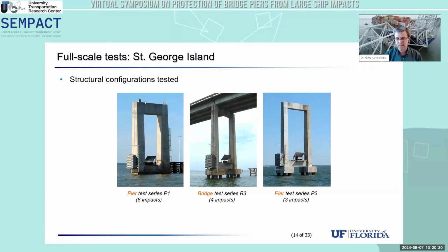The superstructure had been removed. We tested pier 3 in what we call a bridge configuration, where the superstructure was still in place. And then we tested pier 3 again after the superstructure had been removed, because we were very interested in the effect of that superstructure, not only on the generated loads, but also on the response of the structure to those loads.